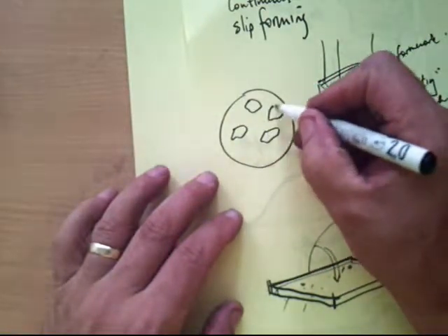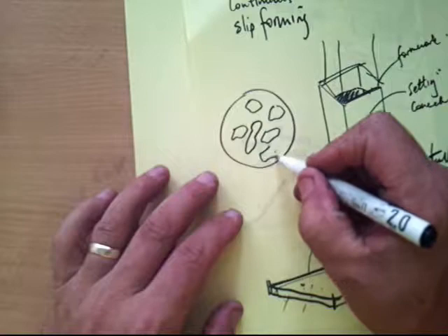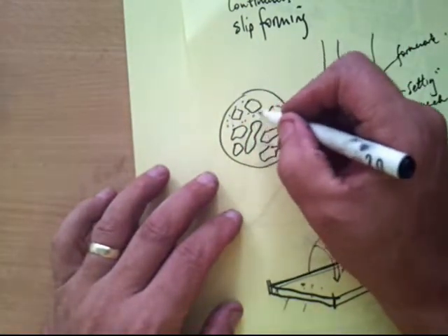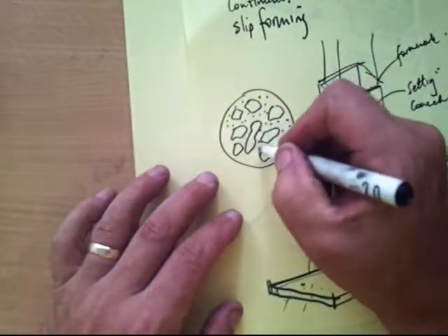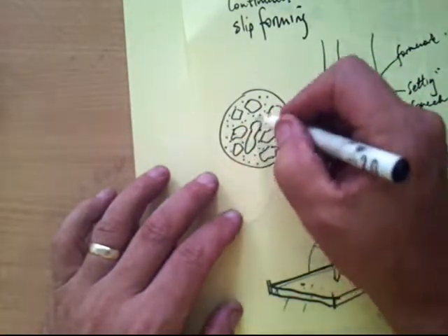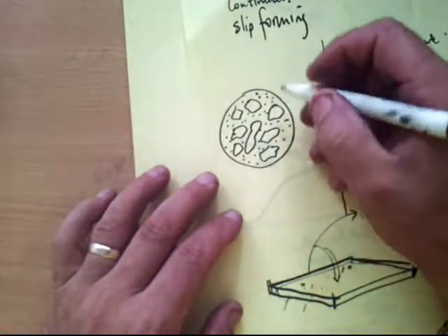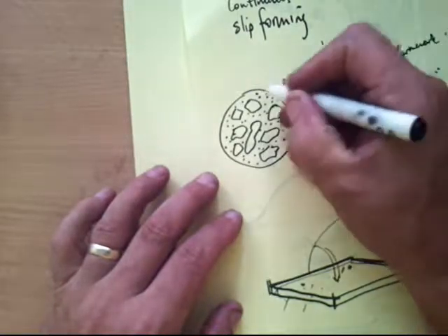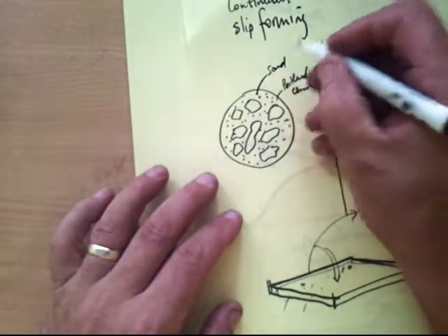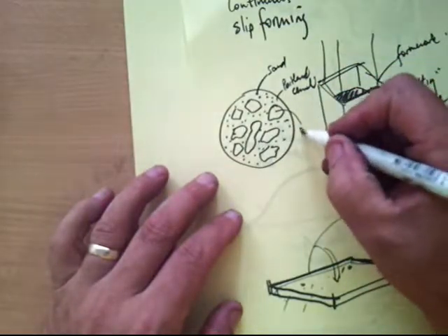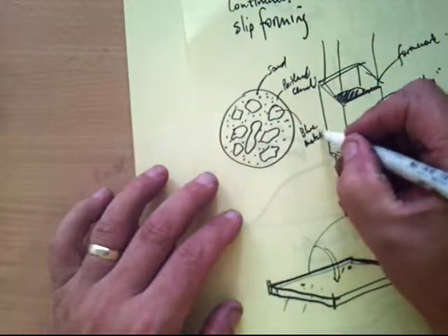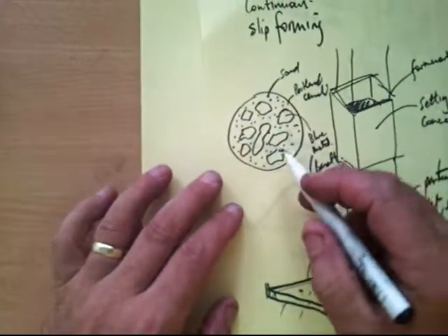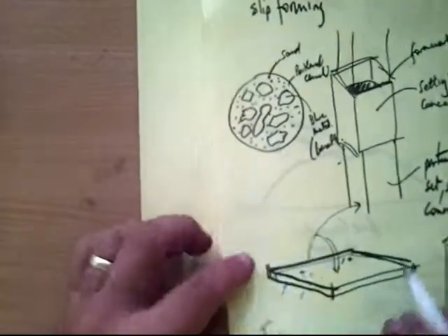Now, as well as concrete being a composite material, and by the way, just before we finish here, if we were to draw a microstructure of concrete, you'd have large aggregate sections like this in place, and they're irregularly shaped, although they can be sized roughly. And then you'd have lots of grains of sand, which I'm doing as dots here to indicate. And the third phase that you see, in between all that, would be the Portland cement. The little dots are the sand, silica, and here you'd have your blue metal or basalt or whatever material is being used.